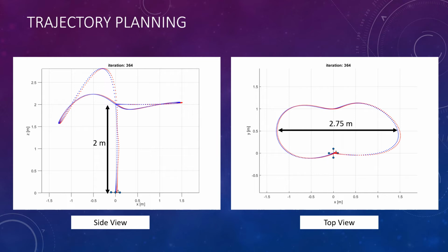To simulate the landing path, we have simulated the trajectory generator, which uses the minimum jerk method to get us an optimum path which the quadcopter can take when it is given points to follow.